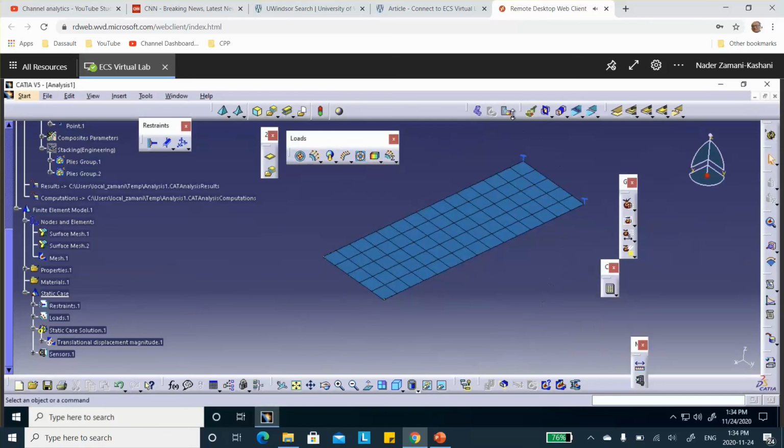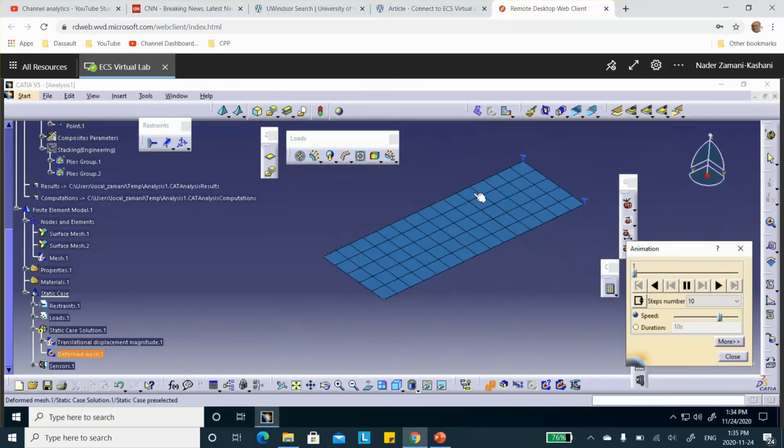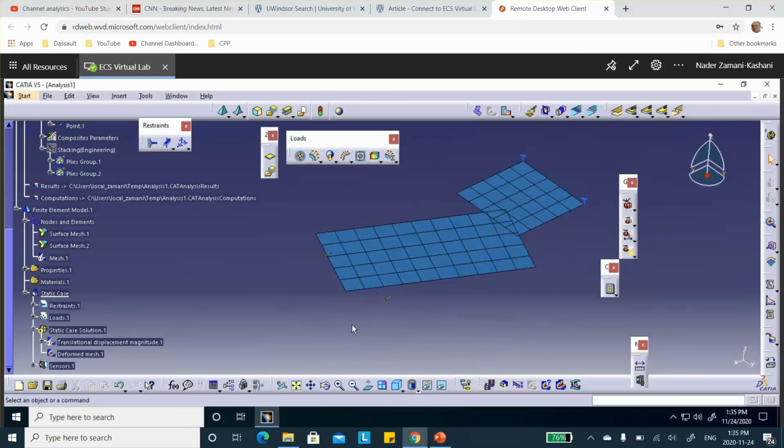None of the displacements or stresses are correct. In fact, you cannot even plot them. But if you plot the deformation, you can see what happened right there. You can see that there was a seam there that it did not know about, so it is subject to rigid body motion, and Catia cannot predict the overall displacement and stresses. Okay, so I will repeat this problem or something similar to it using the zone method concept, and we'll see. Good luck.